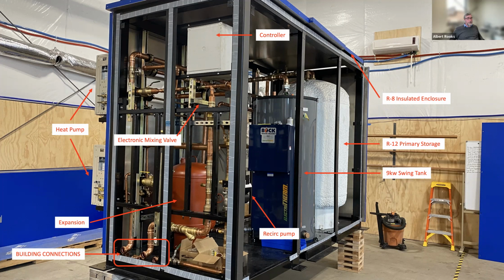We can put the same system in a parkade. It'll slide in an 8-foot clearance. And typically in most parkades, that's fine if we can get in there before the fire sprinklers are up. And we can place it on low profile skates and skate it in. And then if that's a problem, then we can break the heat pumps away from the tanks and start heading more towards a site built system so you can bring all the equipment in.